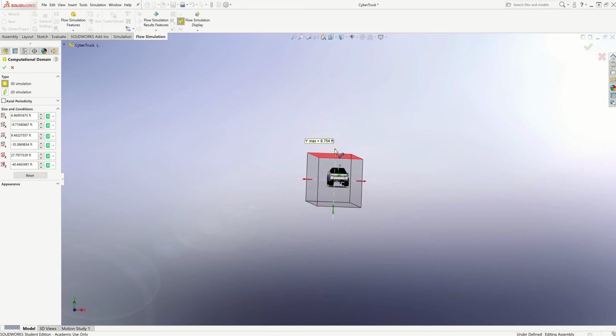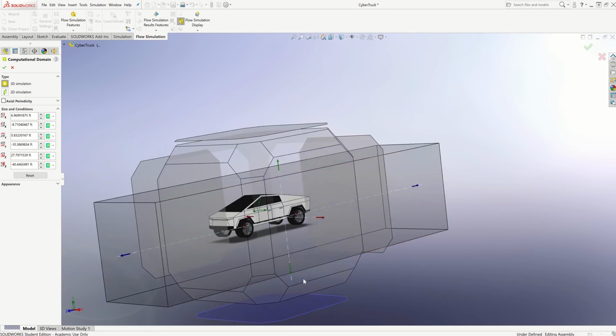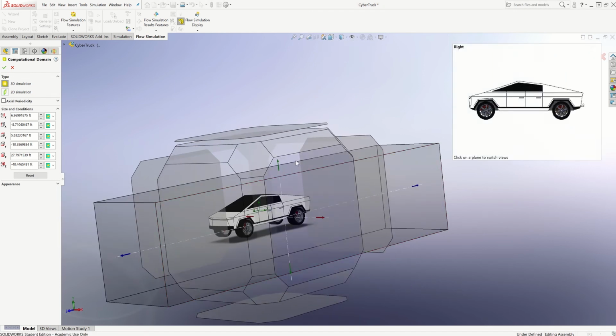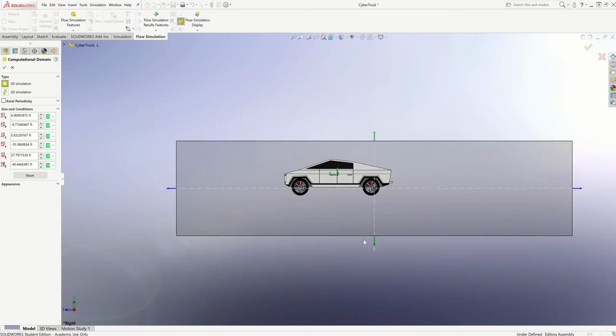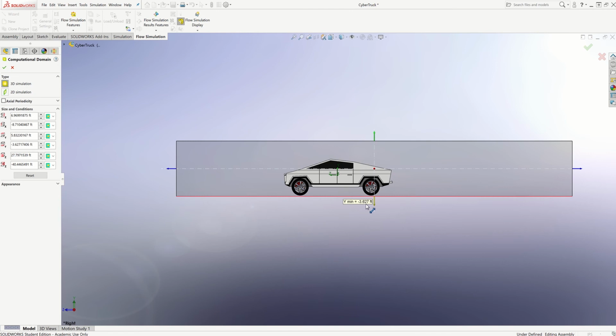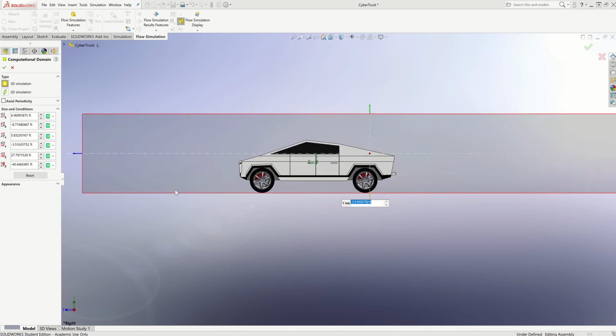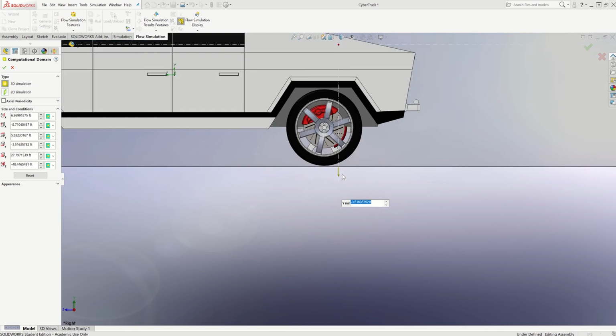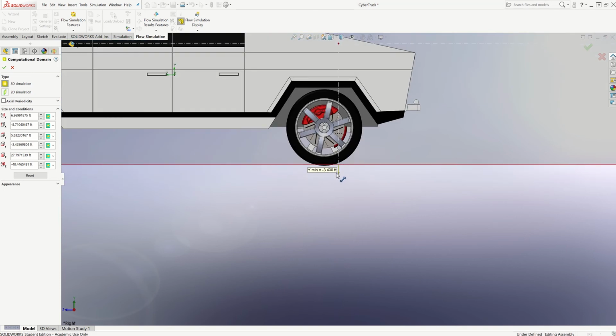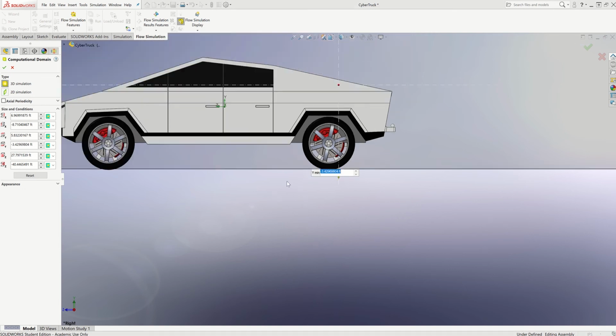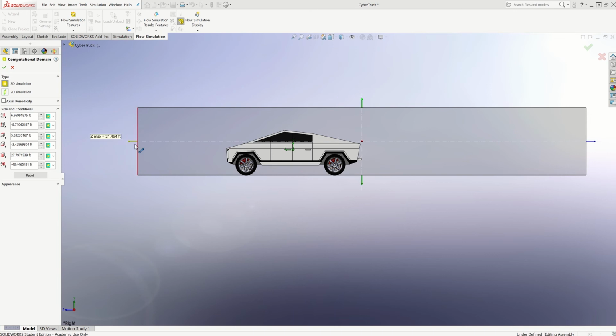We can observe those. So we'll bring this one down and we'll grab, not to hit that box, this view, and bring this all the way up as if it was the floor, because we want to see how the air interacts with these wheels, but we don't want air to pass underneath them. So we're just basically going to bring this as much up as possible at the base of those tires. It's going to fight you a little bit. We got a lot closer earlier, but I'm just going to leave it at that.